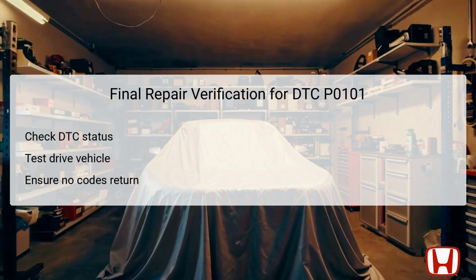It is essential to monitor the vehicle after this test drive to ensure that no codes return, indicating that the initial issue has been effectively resolved. If the DTC does reappear, further diagnostics may be necessary to pinpoint any remaining issues. By thoroughly validating the repair, technicians can confirm that the vehicle's performance and efficiency have been properly restored.